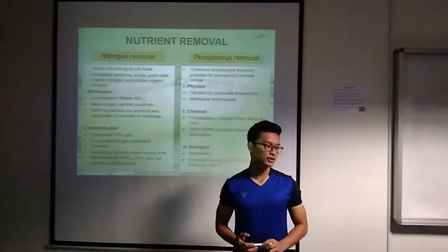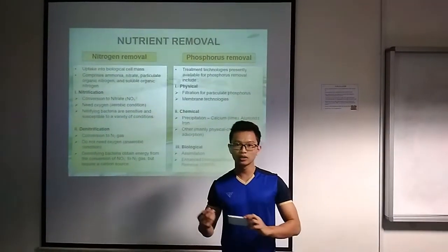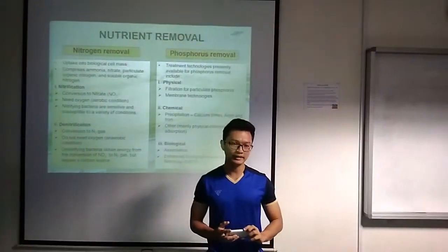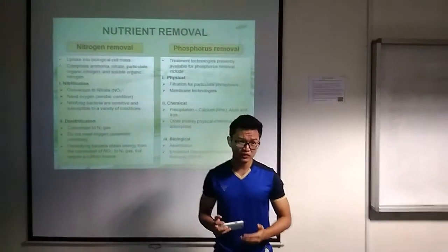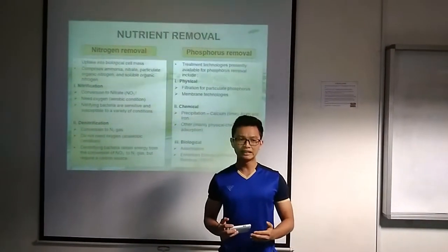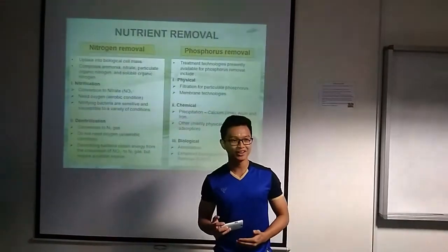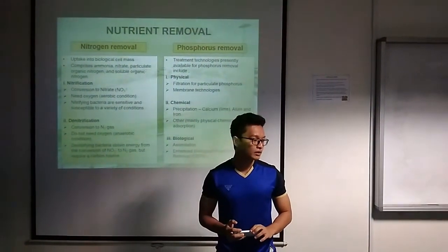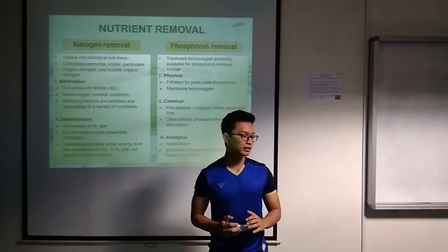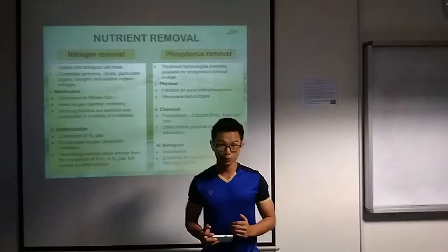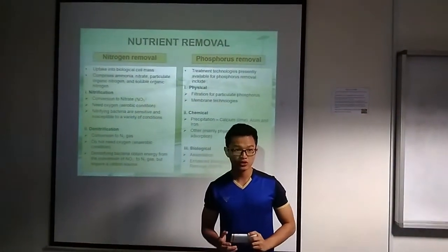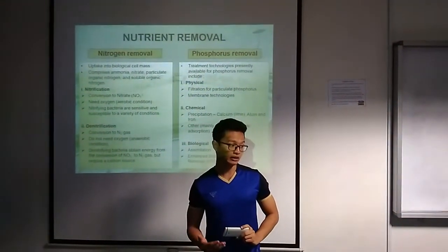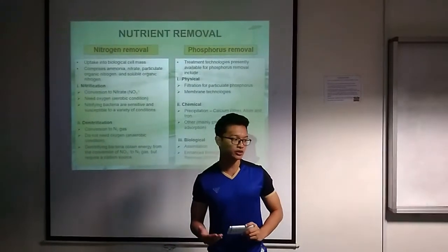Nitrogen removal involves two sub-steps: nitrification and denitrification. In both nitrification and denitrification, bacteria or microbes are needed. Nitrogen removal basically involves uptake into biological cell mass. Nitrogenous compounds usually comprise ammonia, nitrate, particulate organic nitrogen, and soluble organic nitrogen.